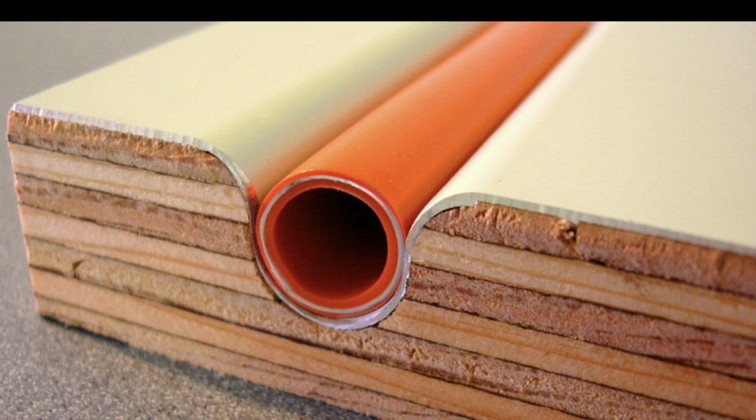If it is an upper frame floor, it's strongly recommended that the use of warm board be employed, which works quite well with the low approach water temperatures, and it also has the ability to overcome any resistance values placed over the top of the heat emitting surface.